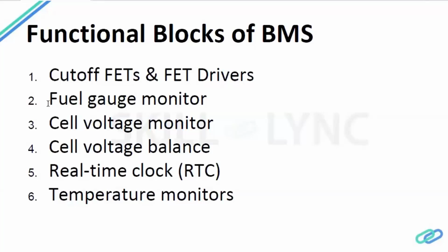But the main issue inside the electric vehicle is that there is no sensor in the world right now which can measure the exact current voltage of each cell while the car is moving, because we can't measure the exact coulomb counting or the capacity inside lithium ion cells. While building a battery pack, it might have 40 or 50 lithium ion cells, depending on what voltage and current we require from that battery pack.